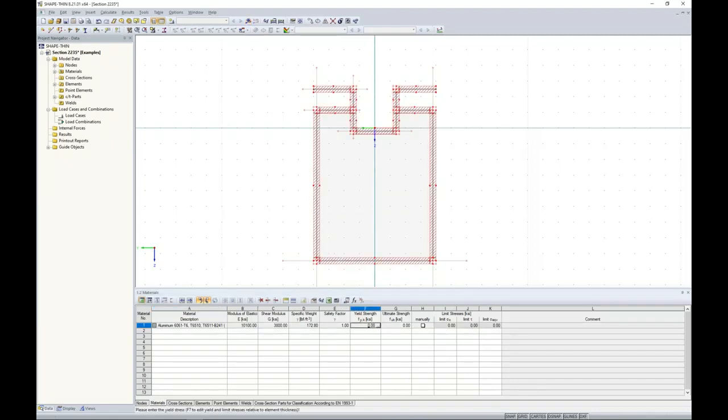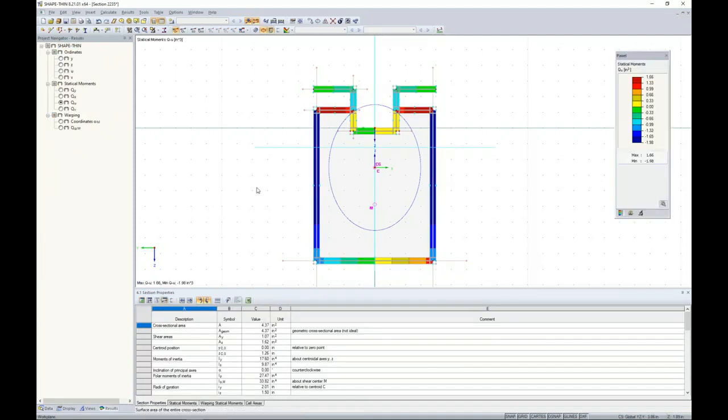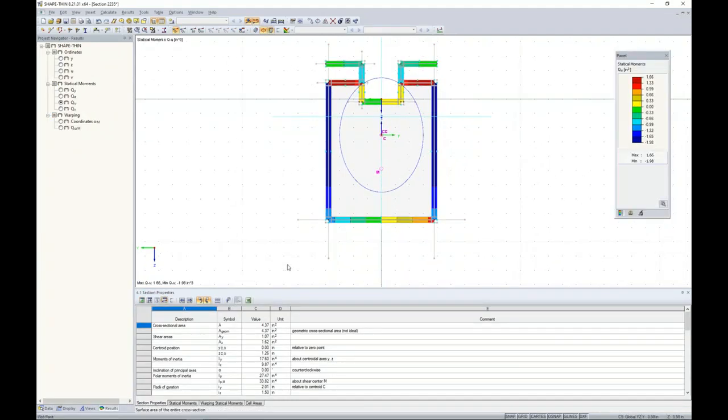Well, the reason for that is because aluminum has different yield strengths depending on if it's for tension, for compression, for shear. So all we need to do is set some type of placeholder here. Fy equal to 30 is perfectly fine. So that's the reason why the program populates 0 there. We can rerun our calculation, and now we are presented with our results.